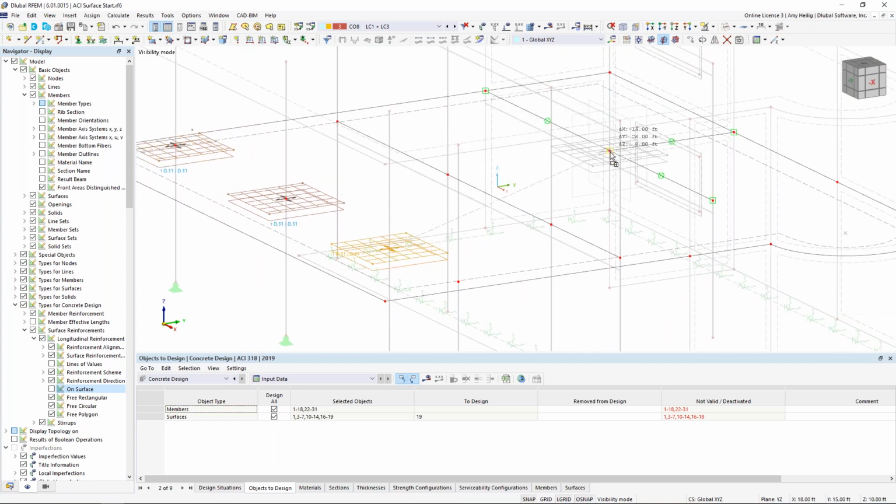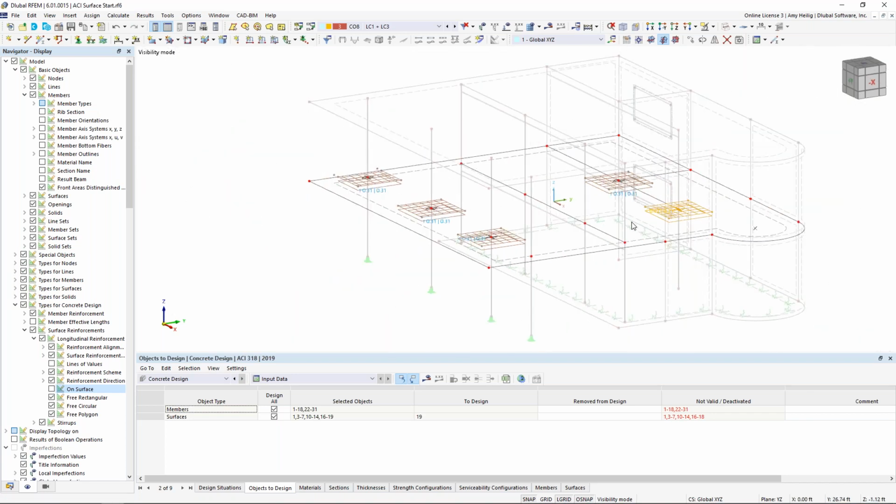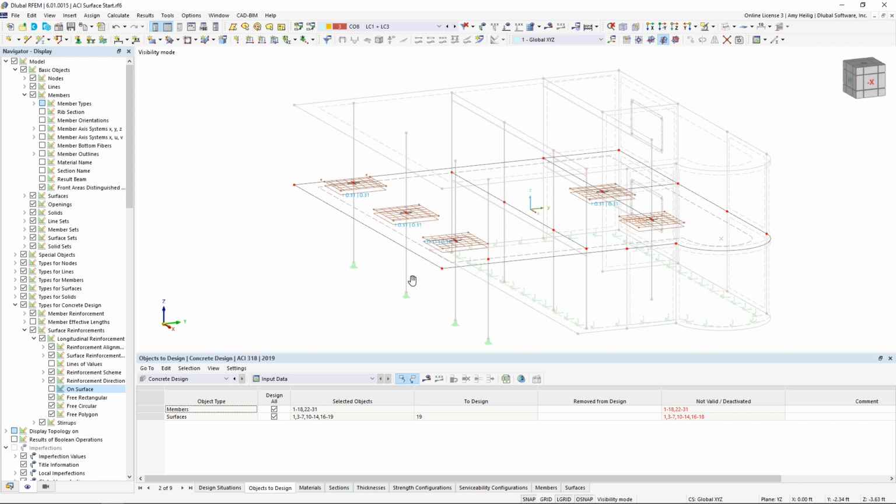I also have some areas back here where we kind of intersect with the walls and columns that need a little bit more reinforcement on the top. So of course we'd want to continue optimizing this best we can based on the internal forces. Again, we probably want to add some shear reinforcement and such to the slab. Now, just taking you to another little side note here, punching shear, this will be ready actually, hopefully in several weeks for the ACI. It wasn't quite ready for this presentation, so we're not checking that right now, but that should be very close to being done within the program.